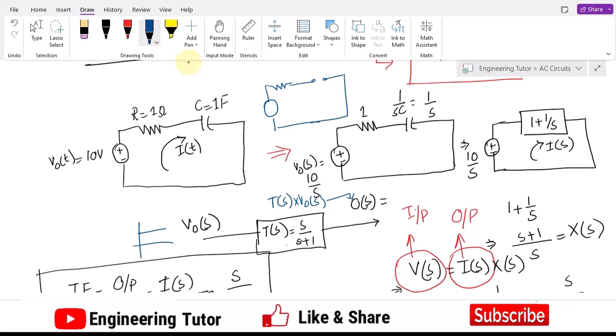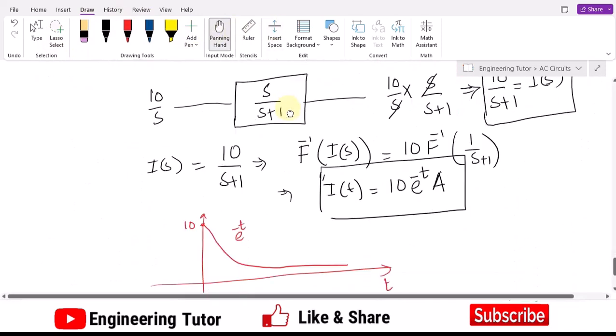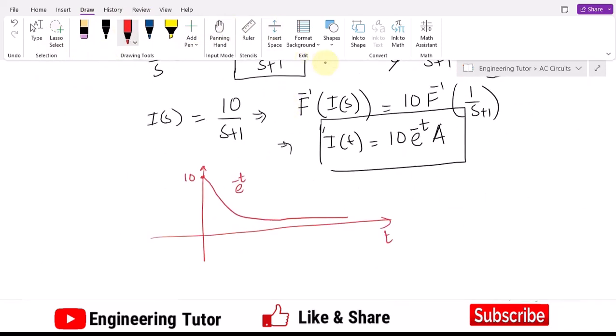Okay. So, it also satisfies the condition that for DC, the capacitor behaves as an open circuit for time approaching infinity. As time approaches infinity, or in the steady state, the capacitor behaves like an open circuit, and the same phenomenon has also been observed here. Okay. In this equation, the same phenomenon has been observed, which is also plotted here.